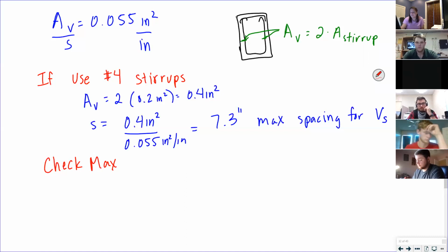So this 7 inches would just be at the ends, where you have the high shear. And this is where you as the designer get to make decisions. You don't want to over-design it, putting one here at 7 and one here at 8.5; you have to create sections of spacing. But that's the next part after this.